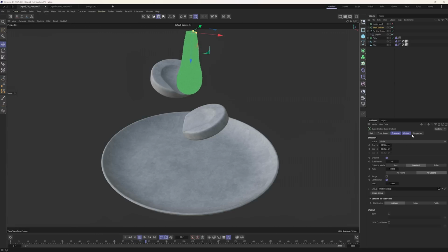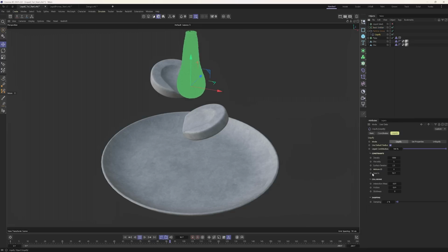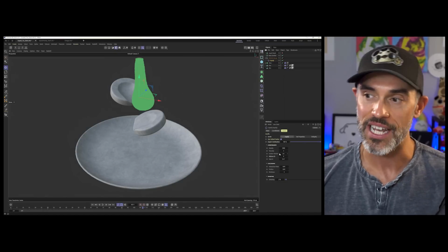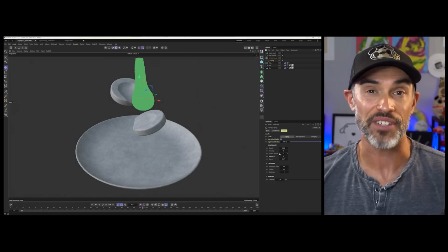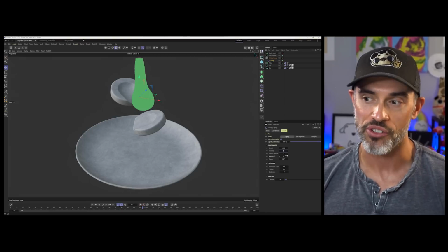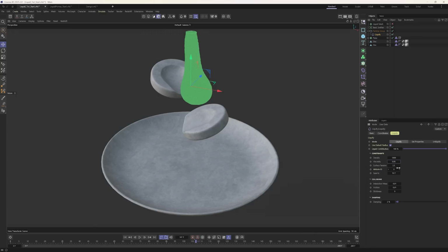And that's because we basically amplified the strength of the viscosity and the surface tension when we upped all those iterations so high. So what we need to do is counterbalance how stiff the simulation's getting with those added iterations by offsetting it with much smaller constraint values. So I'm talking like 0.05 and maybe 0.08 for your viscosity and your surface tension. So we're talking very small values. And now you can see, okay, this is looking a little bit more viscous and liquidy.